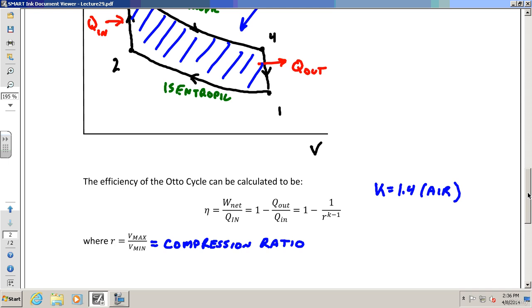And some cars have those. Typically they're more expensive, because people who buy a cheap car probably don't want to pay for expensive gas. That doesn't make a lot of sense. So they usually put them on the higher end cars, with better compression ratios, more power, things like that. So don't put the expensive gas in if you don't need it. You only need it if your owner's manual says so, and the owner's manual only says so if they run higher compression ratios than normal cars. But it's good in some ways to run higher compression ratios, because then you can get more power out. You can have more efficiency.